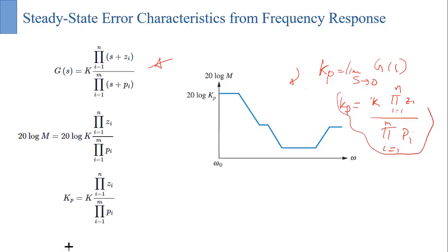So basically the common magnitude. As already in one of the calculation of the Bode diagram, it said that initial curve, if it is a flat curve like this, it actually only gives this magnitude. So we can say that the value that we are getting initially from this flat curve, that is our actually Kp value.